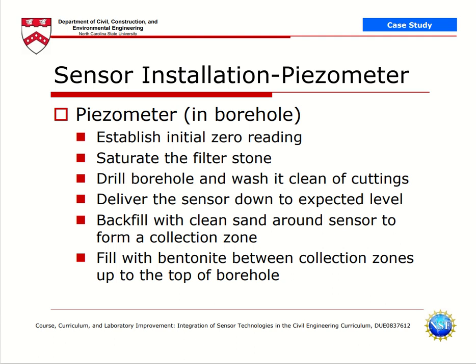Then they lowered the sensor down to the expected level, where it is required to obtain the desirable output. Then they backfilled with clean sand around the sensors to form a collection zone, and finally they filled it with bentonite between collection zones up to the top of the borehole.